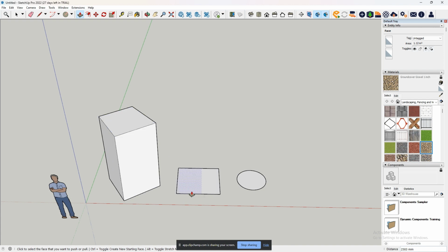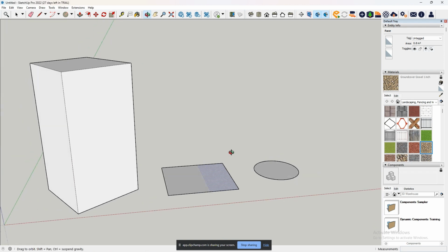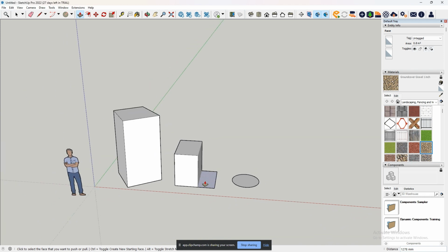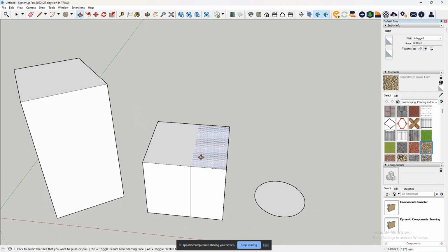And I don't know why that's in two different parts there, but it doesn't really matter. Another thing, just like with all the other tools, you can type in how far you want that level to be. Now, if it ever stops, like this is a really good example, if ever it says offset limited to whatever number it is, you simply want to press Control, and then you'll see this little plus icon added next to that push-pull, and then you're allowed to keep dragging further.